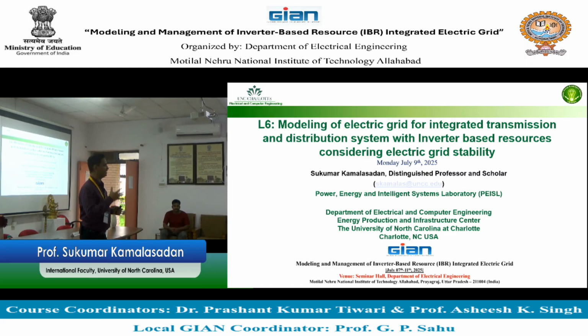And if you see that voltage changes happen in the transformer, I can include that voltage change and then rerun the power flow. Okay. Such power flow models are known as quasi steady state power flow. Quasi steady state time series power flow, QSTS. So quasi steady time series power flow is useful if you want to include slow moving changes.